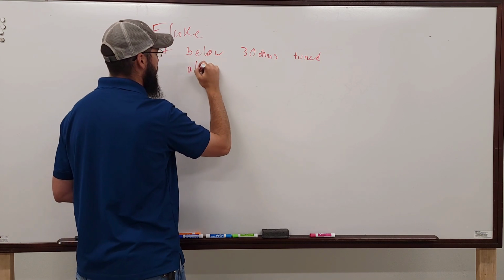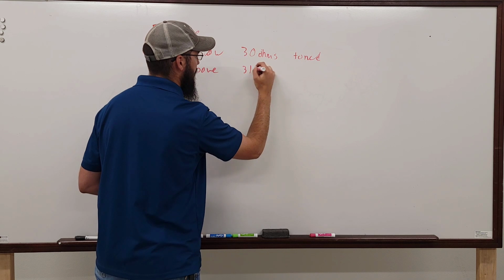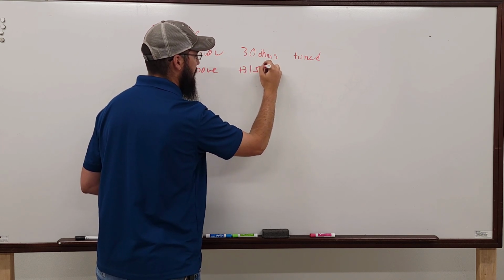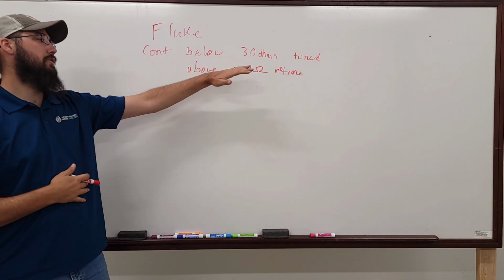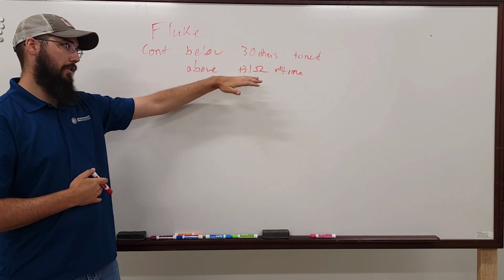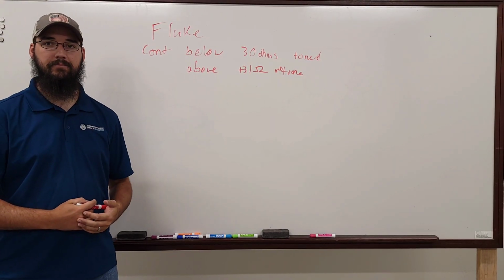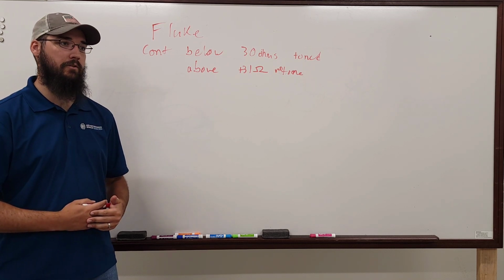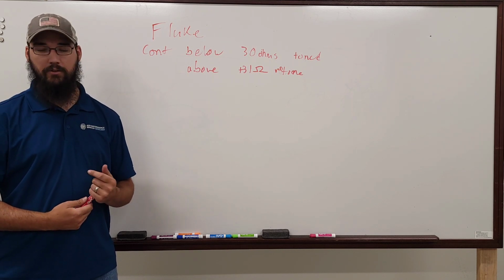Anything above, so 31 plus, no tone. If you've got a motor that has 31 ohms to ground, is it still grounded? Yes. If you're testing that motor via continuity, are you going to know that it's grounded? No. You're not going to have a clue.